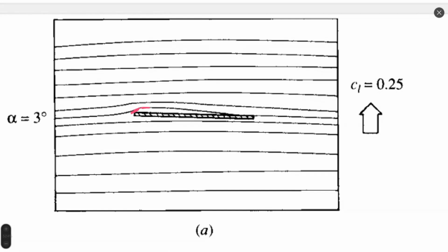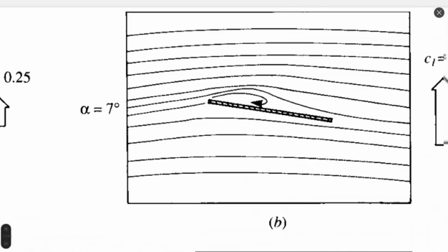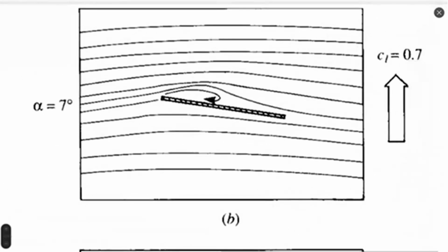You already see that it lifts flow. So it creates local vacuum at the volume on the top of a plate. And this local vacuum, it will destroy all flow structure because it's a very sharp change of pressure. And then you can see on 7 degrees angle of attack already is destroyed flow. It started flow separation because this edge here on the front is sharp.